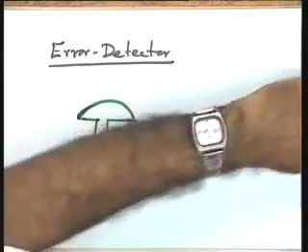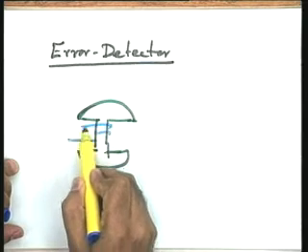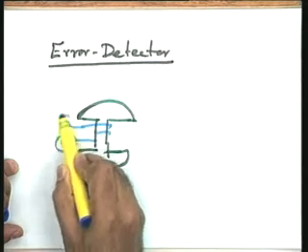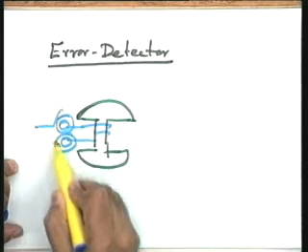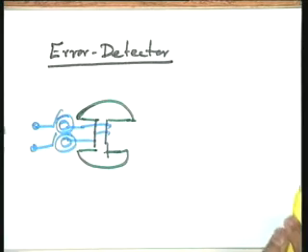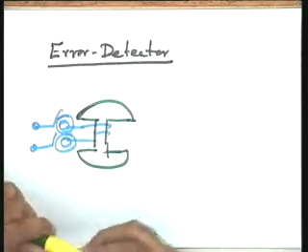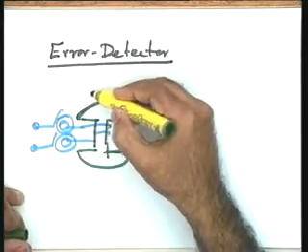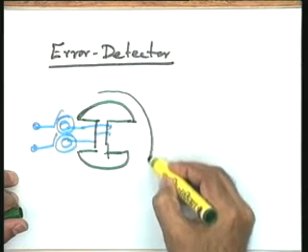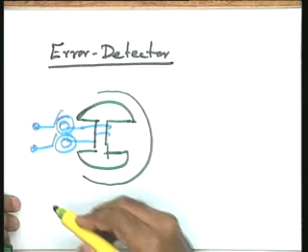On this particular rotor I show a winding, and through the slip rings I give the supply. Okay. Now the stator is a slotted stator, but schematically, if you don't mind, I could show it this way. This will make my derivation of the mathematical model more clear.